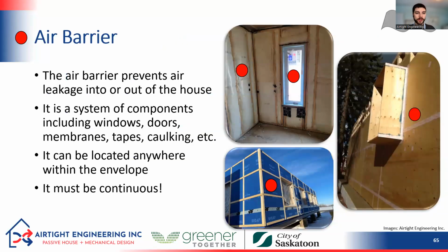Speaking of air barrier, let's talk a little bit more about it. This is a part of our building envelope that's maybe a little less well understood. Our construction industry has been doing a lot of great work in terms of the vapor barrier. For many years, we're probably all used to that clear sheet of 6 mil poly right behind the drywall. That's our vapor barrier. But there hasn't been as much attention given to air tightness necessarily.